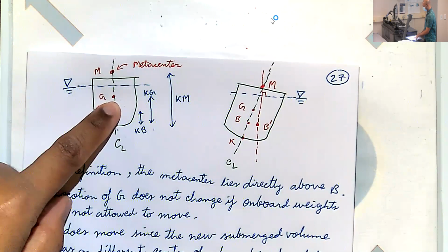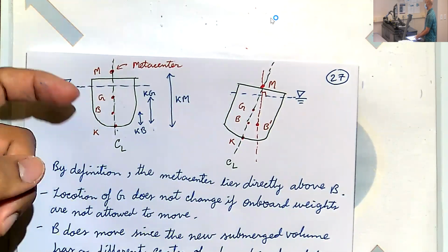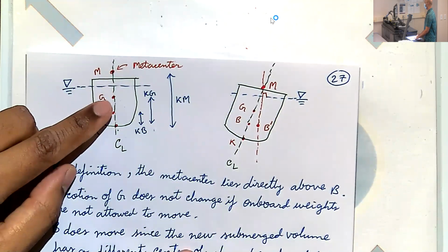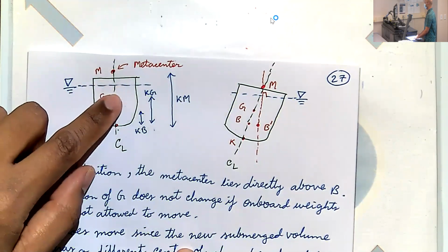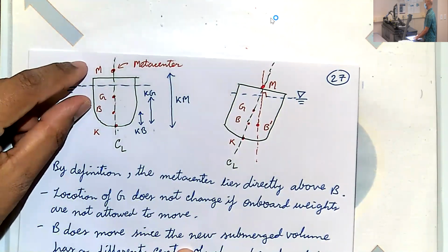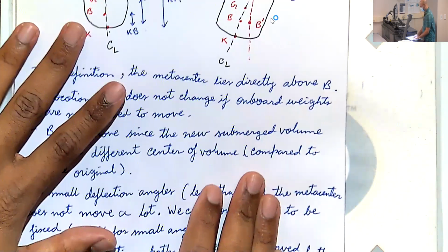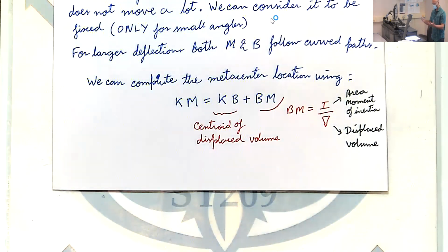It'll be an unstable equilibrium. Even a very slight disturbance will make it roll over. So it's very important whenever you design a hull to keep GM positive at least, and larger if you want a very stable hull. Of course, there are always pros and cons anytime you make it too stable, and we'll talk about that in a second.